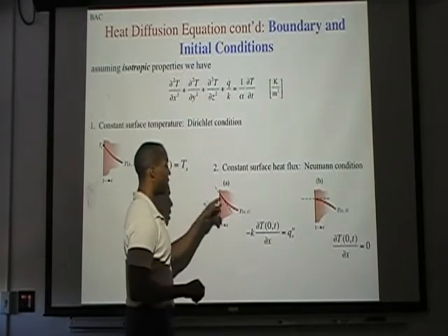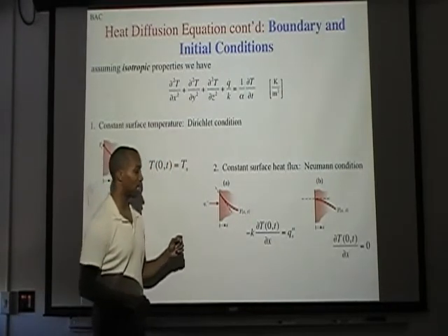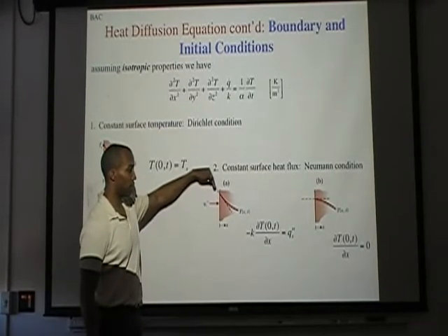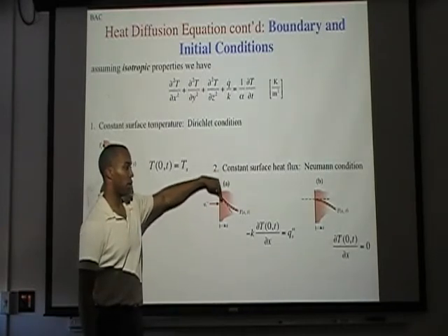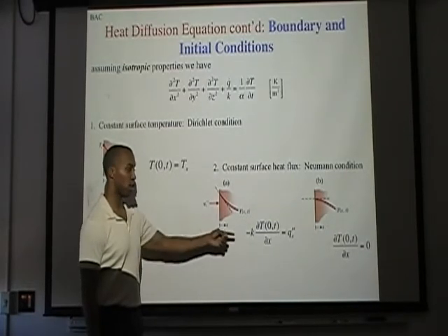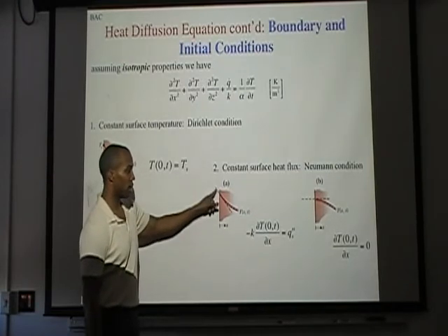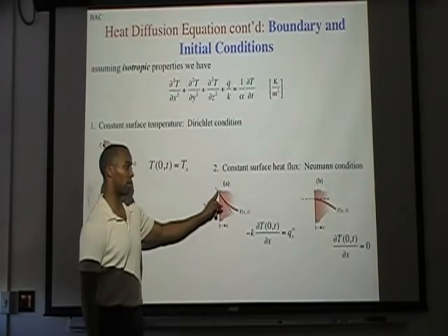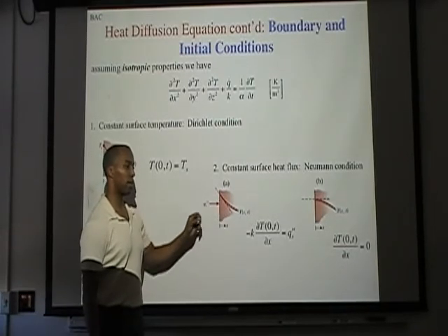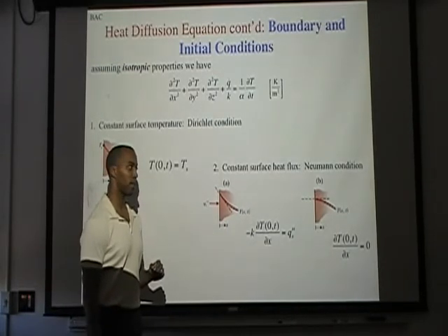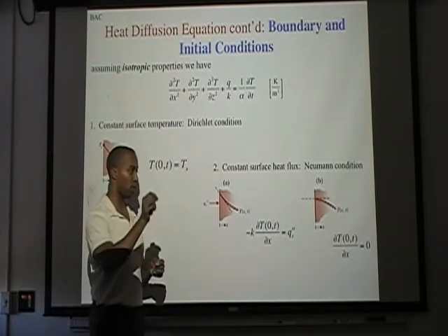Whereas for a constant surface heat flux, and we'll see this more later, at the surface here we're balancing Fourier's law to determine the heat flux. There's a constant slope that this line has to come to. So the temperature profile has to come to this slope here that satisfies the boundary where Fourier's law is applied. And that slope is important. We're going to have to learn to draw these slopes throughout the course.